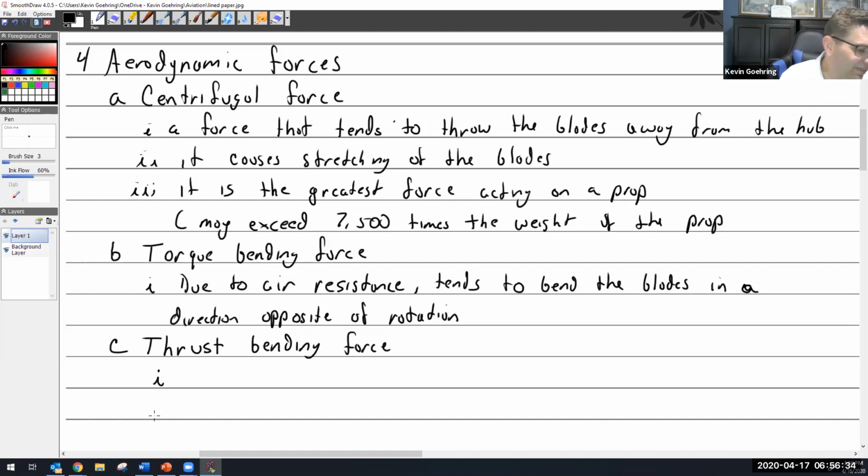When I was considering, for a small period of time while I was drinking heavily, purchasing a 182, which I'd still love to have, that was one of my big things. I'm familiar with engines, so engines don't necessarily scare me, but they scare me enough to know they're really expensive. The first thing I looked at was, what's the TBO on the prop? How long has it been since the prop was overhauled? Because that's a huge expense. Imagine you get a great deal on a 182 and only spend $70,000 on it, and then 6 months later you need to have your prop overhauled for 20. That's a pretty expensive plane.